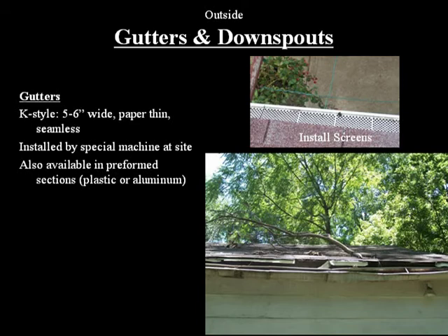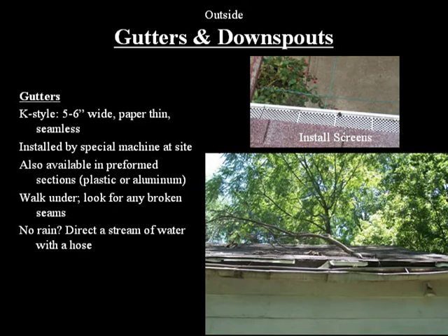The best way to look for problems is to walk directly under your gutters. Ideally, the best time would be during rain. But if you need to manufacture your own test, direct a stream of water with a hose and watch for leaks.